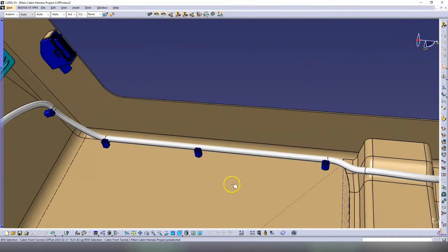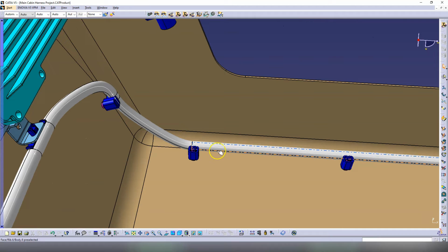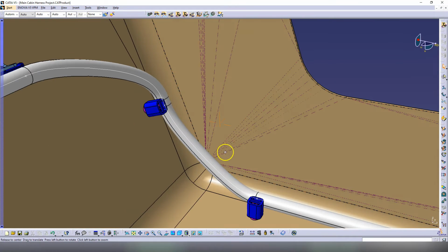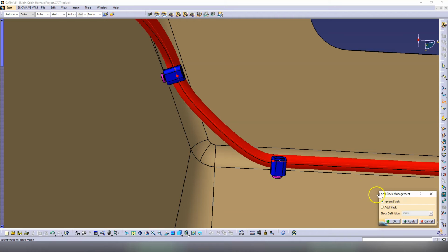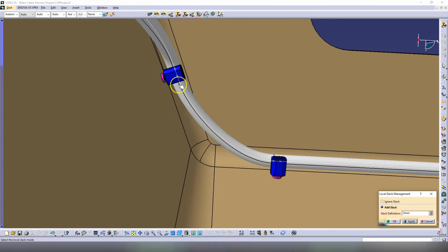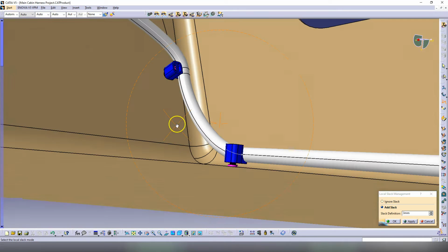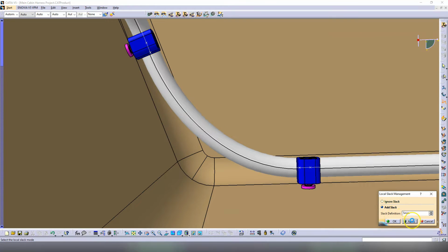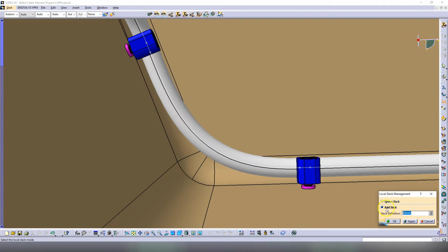So this doesn't need slack. This, you need to check manufacturing tolerance here. There are some things around here. So this one, we fix this with slack. So this needs to go on the body in white. You cannot have something like this here, because the carpet is going to follow the body in white. So you cannot have this, this needs to go very deep, like very deep, 10 millimeters. Just needs to sit on the